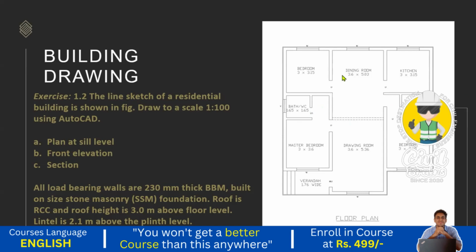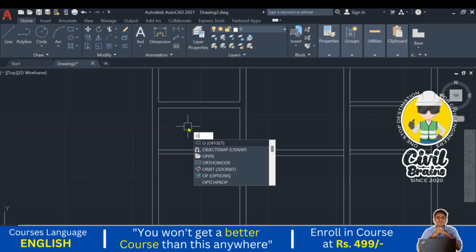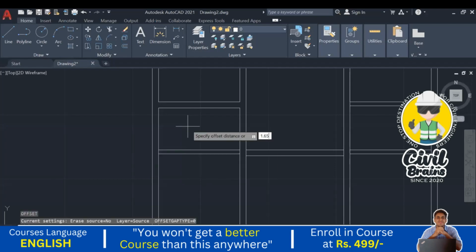Correct? Okay, so everything else is done. So these two partition walls: from this wall it is 1.65 and 150 mm, and it is 1.95 and 150 mm. Okay, we'll draw that one. We'll go to the offset command again. Offset 1.65. Press enter. And offset 0.15. Okay, this extra thing we will just delete.